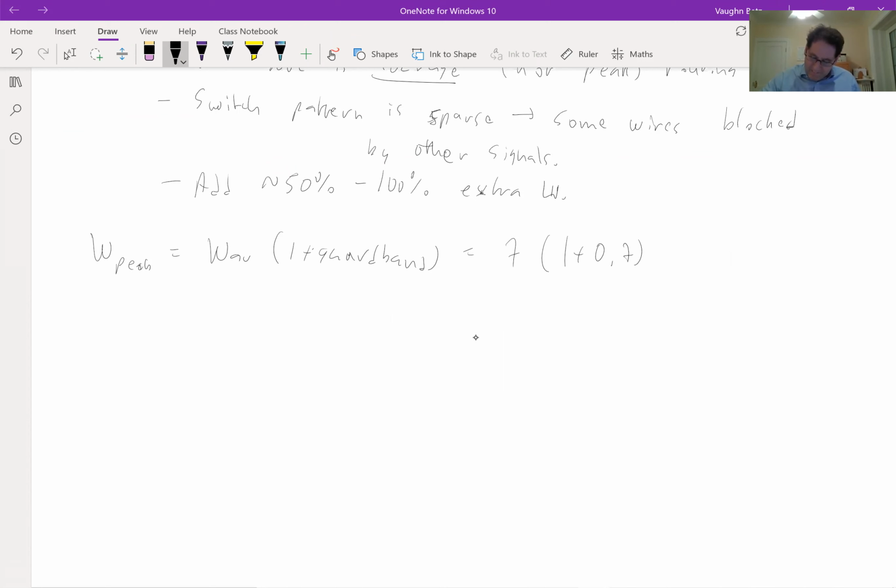Then we get 12 wires per channel, which is a pretty reasonable number for a simple logic block like this. Like for a 4-LUT, it's a pretty simple logic block. Lambda's small. You can actually get by with pretty narrow channels. If you look at commercial FPGAs, their channel width is usually 200, 300, kind of 400, those kind of numbers. But their logic blocks are those big cluster-based logic blocks. Because we've chosen a much smaller logic block, we can get by with a much smaller channel.